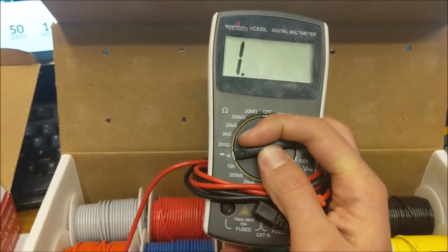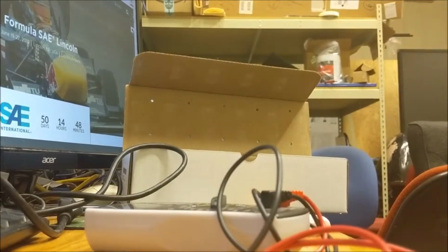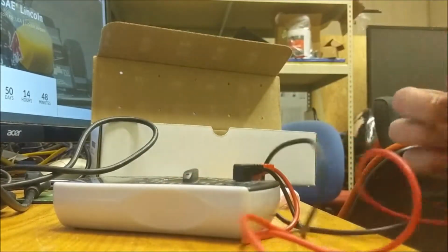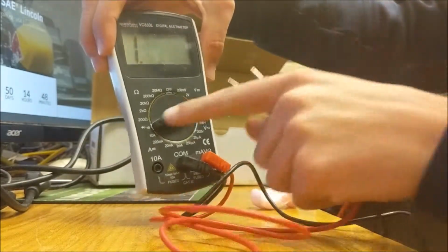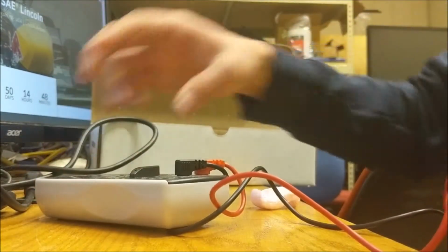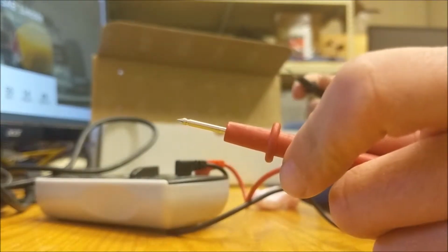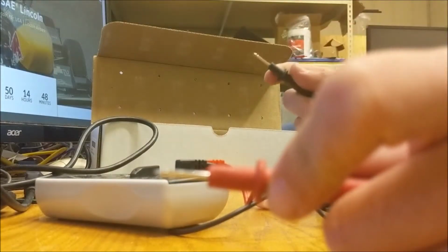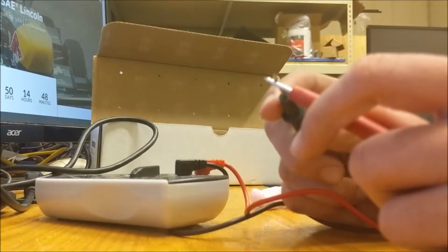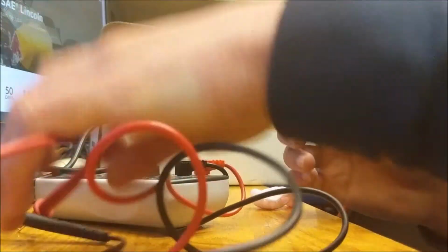Furthermore, you can do a continuity test. The continuity test is easy to run. You just do this by setting your multimeter at the continuity test symbol or diode symbol. Then you can touch one end of the multimeter to one end of the wire and the other to the other end. If it makes this noise, then you're making connection. If it doesn't, then there is no connection. You should check or replace your wire.